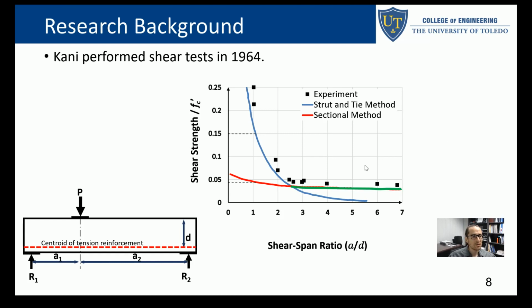So shear span to depth: shear span is the distance between the support and the point load. Depth is effective depth, so this plot shows that.